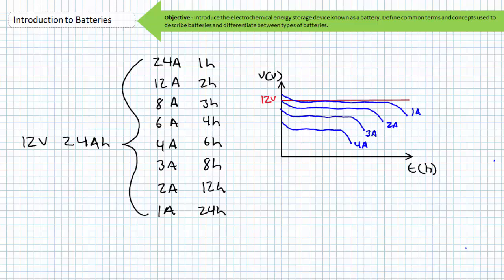These observed effects should come as no surprise. Those that have trained for an athletic event are no doubt aware that a weekly regimen of hour-long training sessions have nowhere near the intensity of a 5-minute fight. It would be expected that a 24 amp-hour battery being asked to supply 24 amps at a dead sprint wouldn't last the full hour. Additionally, as the battery reaches the limits of its capacity, the electrochemical reactions central to the process could be expected to slow down as active material and functional surface area are consumed. To further complicate matters, with increased current draw, the output voltage is reduced because of a voltage drop across the internal resistance of the battery. We'll discuss the dirty details of discharge characteristics in later lectures.